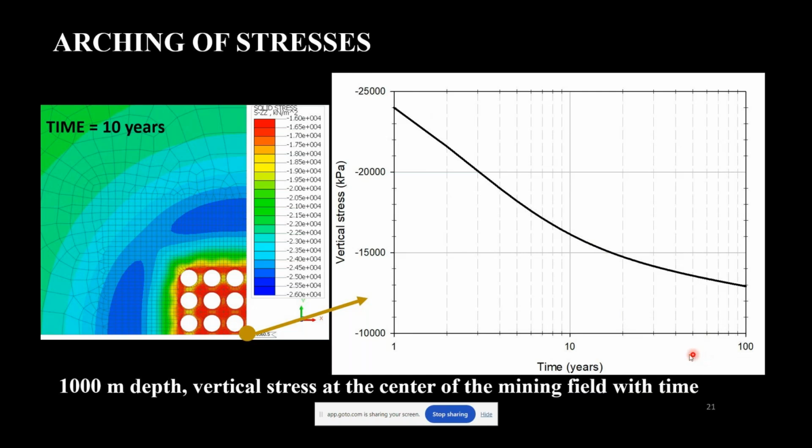However, if we use a more advanced model, this could be different, because as we increase the shear demand in the overburden rocks, we would expect at some point to have plastic deformations and cracking of the overburden rocks, and this would affect the results for sure. But in this model, we are assuming that there is no plastic deformation in the overburden rock.